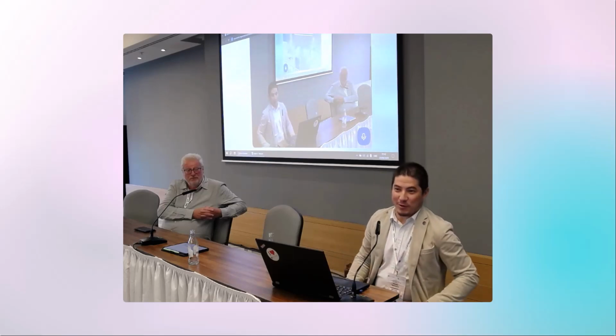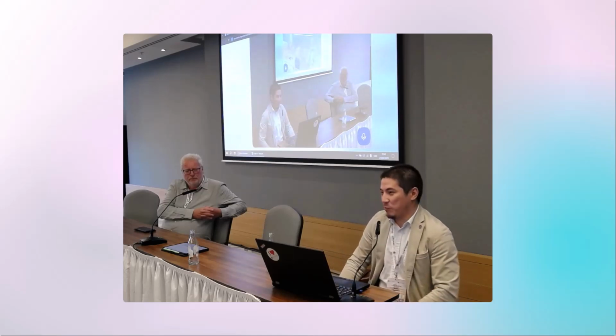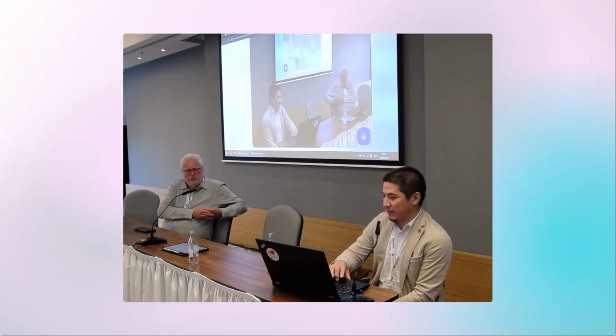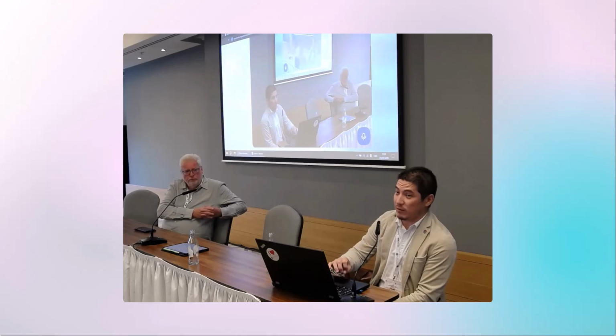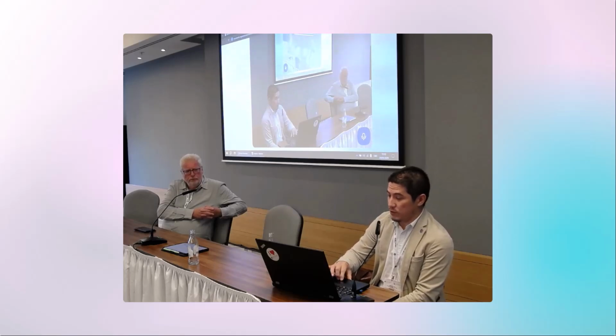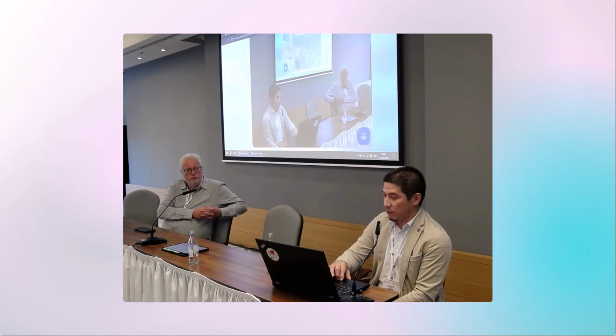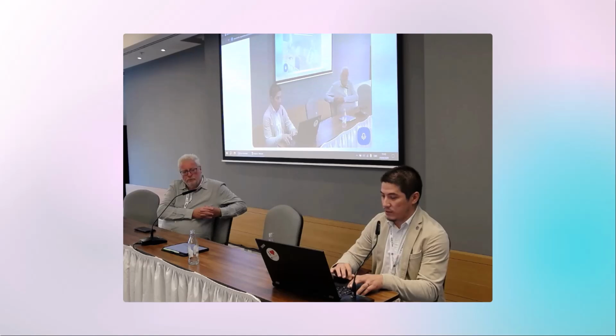So, thank you for your question, Paolo. Of course, you need to check the IFC schema for that case. You have IFC window, and if you are familiar with property sets, you go down, there is a related property set for glazing properties, especially. Window panel properties as well. Glazing type.